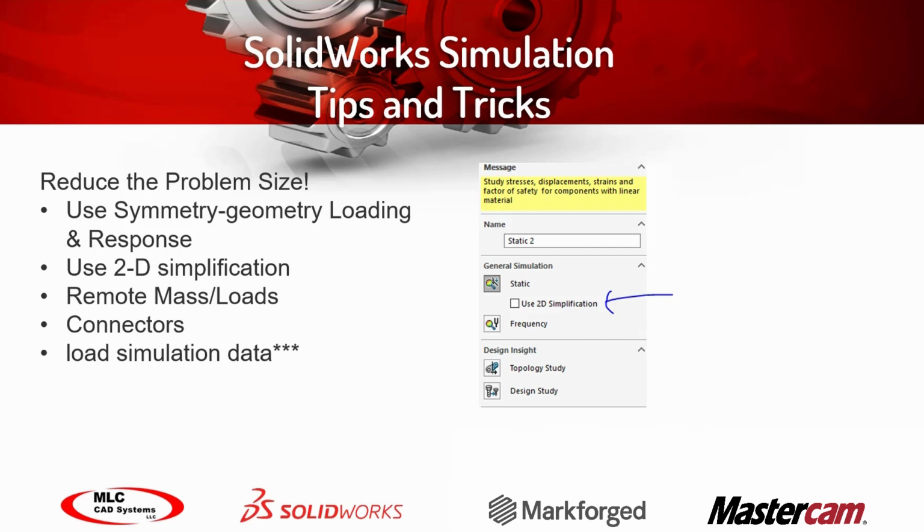If you don't need the results on a component but want to get a load from it, we can take advantage of the remote mass, remote load, get the inputs but not have to mesh it. So that saves a lot of time as well. Another way to save time would be to take advantage of connectors.